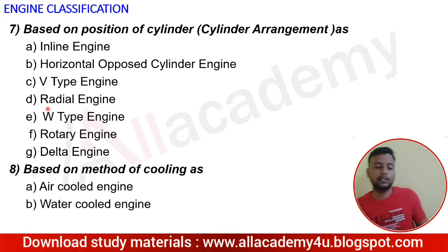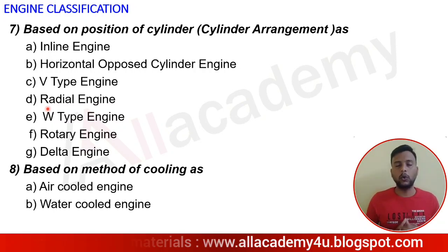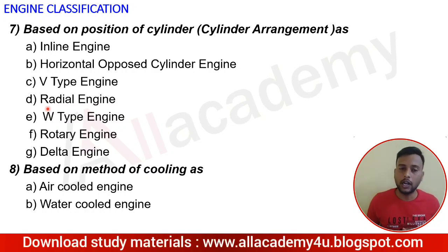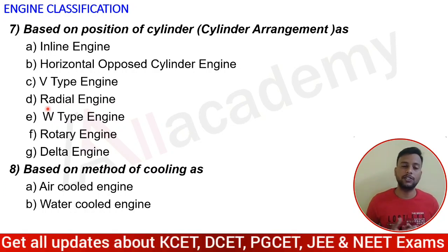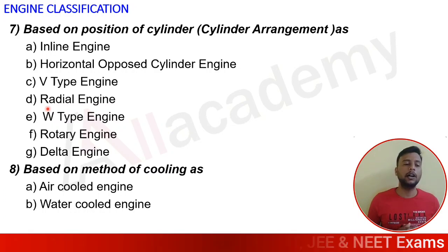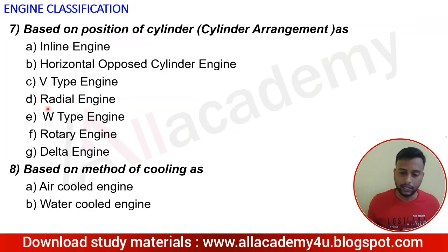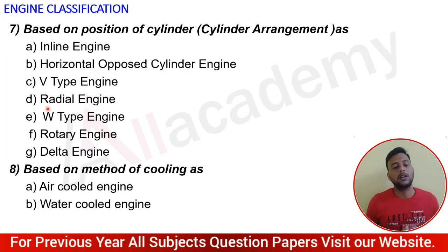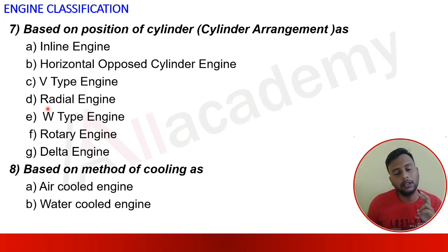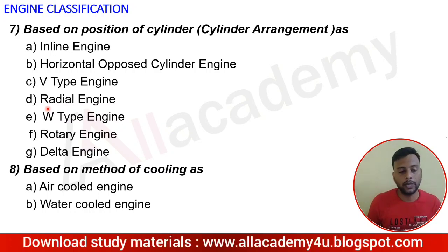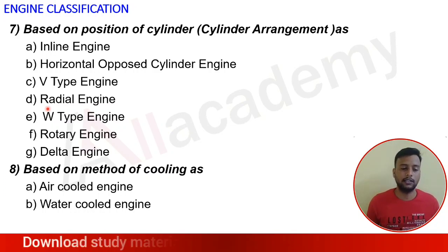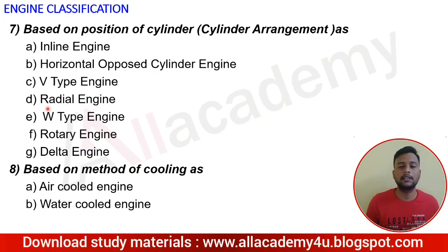And the last one is the method of cooling. Cooling plays a very important role in any automobile engineering, because if there is no sufficient cooling, obviously there will be less efficiency and failure of the engine will take place. Now, based on cooling there are two categories. One is air cooled and the other is water or liquid cooled. Okay, it's not exactly water, I can say liquid cooled.